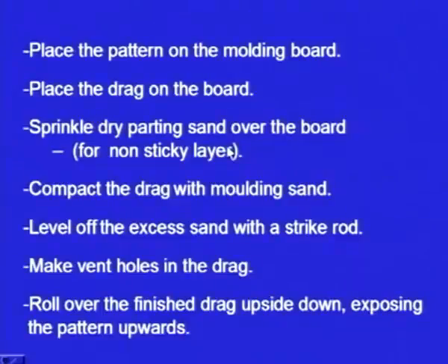The dry parting sand is fresh silica sand. So this will be free from clay, free from any other dirt particles and moisture. And why do we have to sprinkle this dry parting sand? Because we are going to place the molding sand over the molding board and the pattern. And after molding is over, we have to withdraw the pattern. That time the pattern should be withdrawn easily.